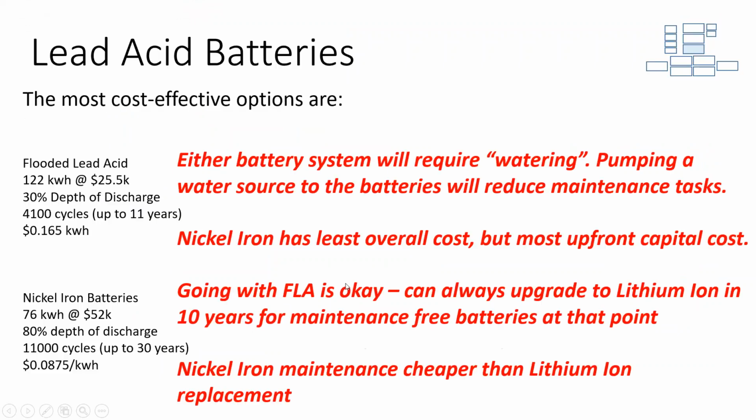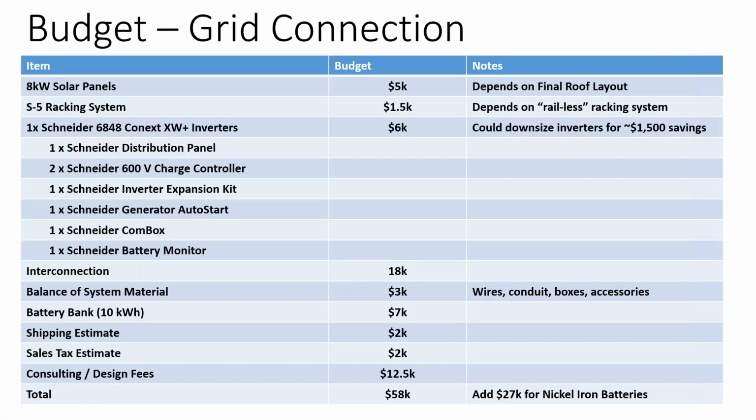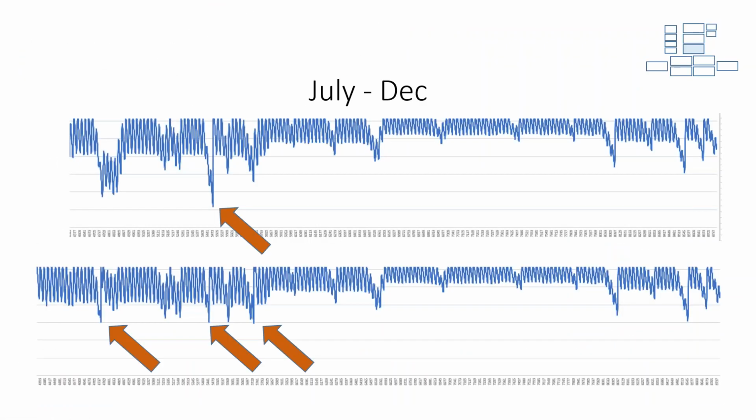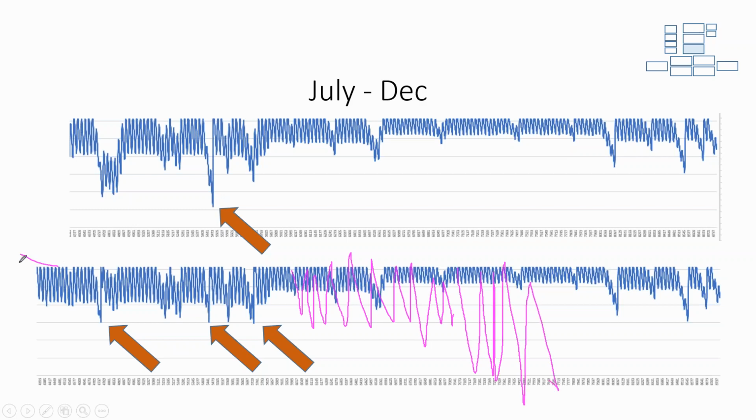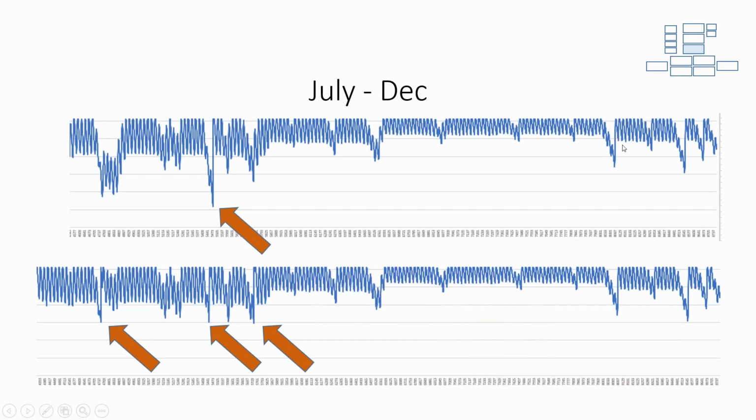Now, for that matter, when we were evaluating the different sizes between the different batteries, we had another nickel iron battery that said, look, whereas with flooded lead acid you really want to operate in the top end of that range, with a nickel iron, they have no problem doing a daily deep cycle down to 80%. And so the size of the battery bank could be smaller. But that said, we would be starting our generator much more frequently and relying on our generator much more often.